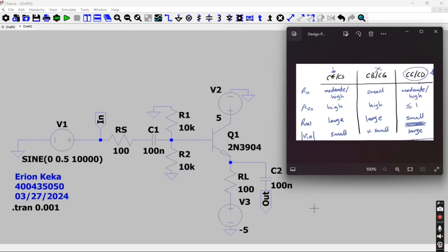Finally, the BJT is simply faster than the MOSFET due to featuring a low capacitance on the control pin. These reasons make the BJT better suited for this application in this design project to satisfy the given requirements.